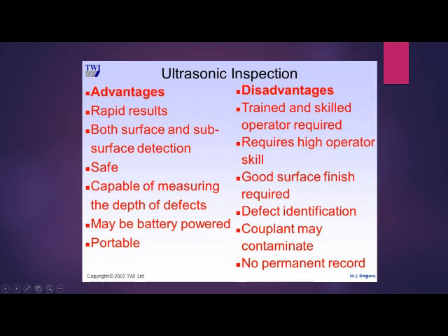This is the ultrasonic inspection advantage and disadvantage. For advantage, there is rapid result, both surface and subsurface defect detection, safe, capable of measuring the depth of defect, may be battery powered and portable.